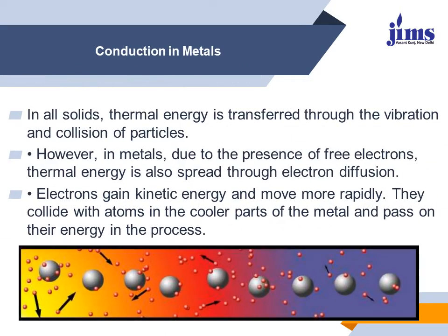Conduction in metals. In all solids, thermal energy is transferred through the vibration and collision of particles. However, in metals, due to the presence of free electrons, thermal energy is also spread through electron diffusion. Electrons gain kinetic energy and move more rapidly. They collide with atoms in the cooler parts of the metal and pass on their energy in the process. So we can say conduction takes place in solids, gases, and liquids also.